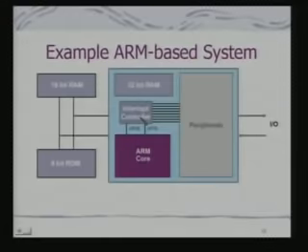You have got the interrupt controller to which the peripherals are connected. Via these peripherals you actually connect the IO devices, okay, and this peripheral generates these signals for the ARM core. This is on-chip 32-bit RAM which may have the device handlers, that is your device service routines, as well as your stack as well as your vector, and these are the external memories.